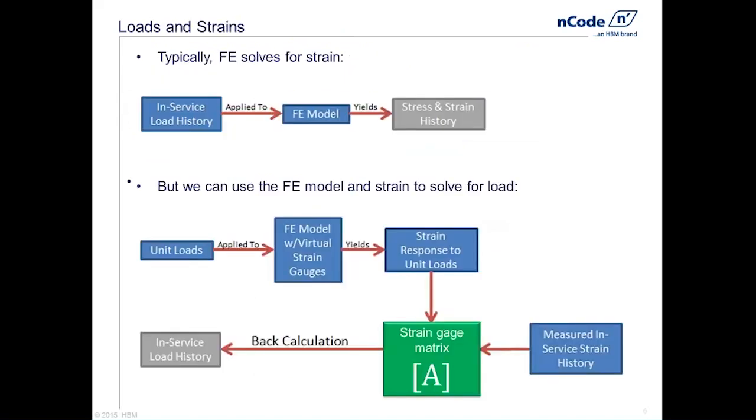So let's think about how loads and strains are related, or loads and stresses. Test engineers talk about strains a lot because they use strain gauges. FE analysts talk about stress a lot because that's typically what they look at when they look at pretty pictures on a contour plot. So I'm going to use the terms stress and strain just interchangeably today during this presentation. Typically speaking, if you're doing finite element analysis, you have the route that's shown up at the top here, and that is that an in-service loading history that we apply to a finite element model tells us local structural response. So we can figure out stress and strain response based on some analytical approach.